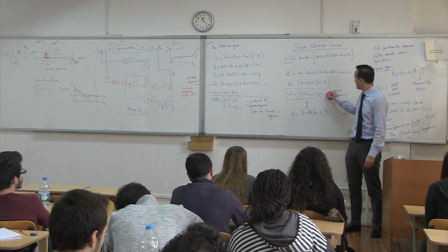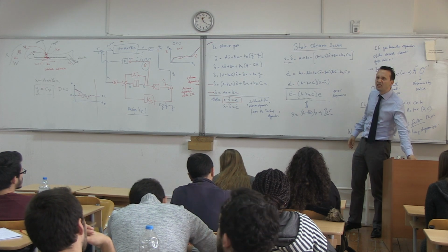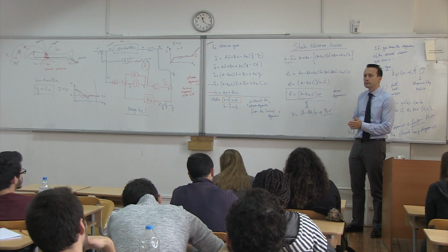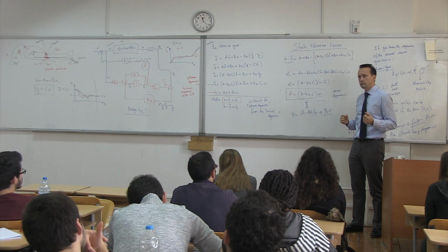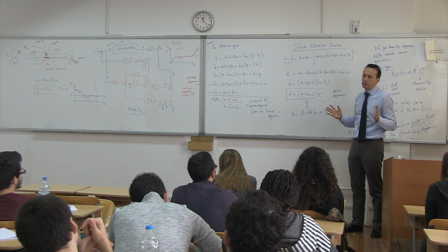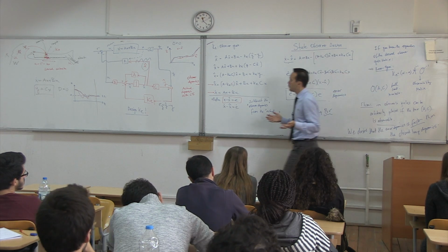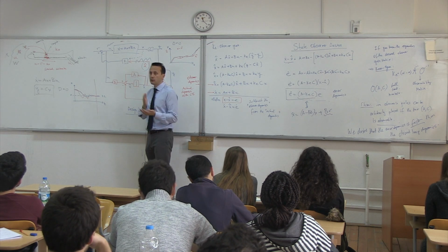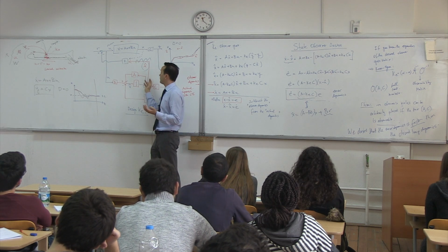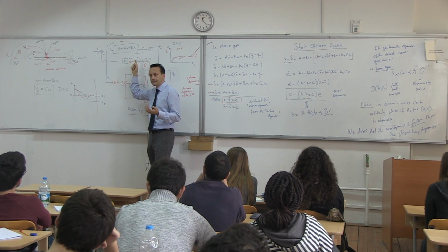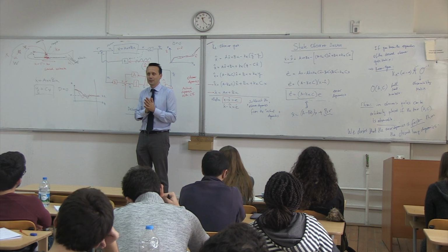Any questions? Yes? For the same equilibrium point, isn't that B and the other B is the same? Yeah, at the equilibrium point, yes. For the same equilibrium point, we can say that both A and B's are the same. Yes, and therefore there's no error. Maybe you don't really need an observer. If these B's and A's are the same at the equilibrium point, and they are, then the observer will see 0 error, and you will have perfect x hat coming from here. The problem is, first, they are not. I'm sorry, you're not always at the equilibrium point.